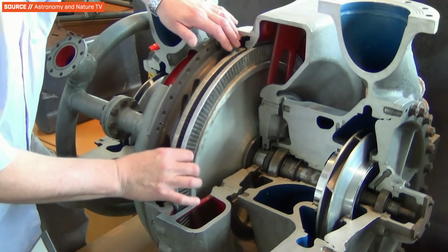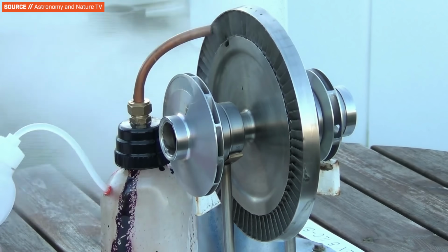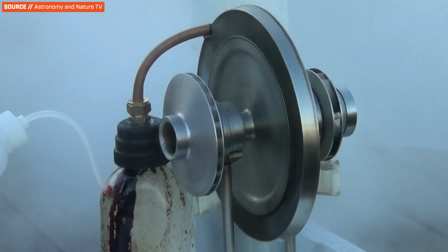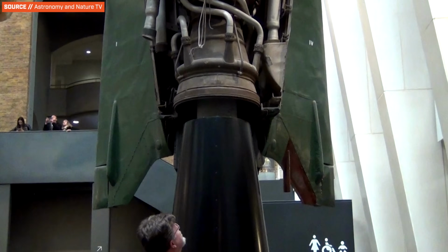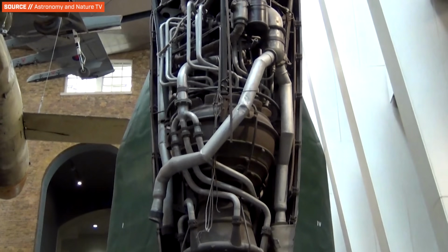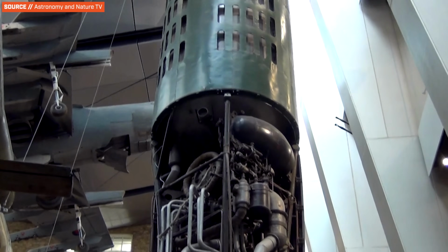One of the earliest examples of this was the German-designed V2 rocket with the A4 engine. Instead of utilizing the main propellant, they basically used a monoprop rocket to spin the pumps. They chose high concentration hydrogen peroxide as the fuel, and then they ran it over a potassium permanganate catalyst that can create enough energy to spin the turbine up to the right speeds. I like this solution because it's using a simple pressure-fed monoprop rocket engine to spin a larger, more powerful pump to increase the overall output of the engine.